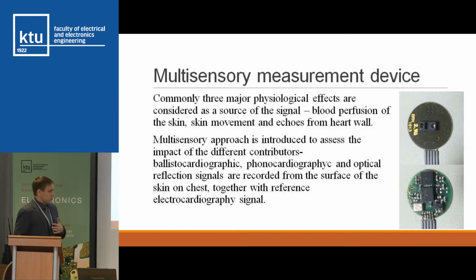This device was attached to the body with a standard EEG electrode attachment, and we measured the heart aortic valve acoustic signal, movement of the skin by means of an acceleration sensor, and optically we measured also the amount of blood in the skin by means of the reflection coefficient of the skin itself, which is basically a reflectivity test in the IR and red light range.